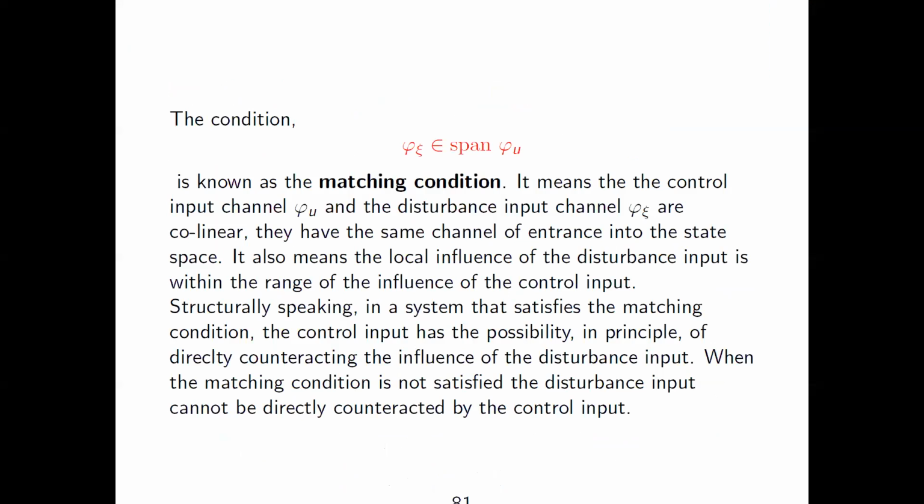Yes. Well, when you were talking about the matching condition, I thought you mentioned singular perturbation, and also the application to the DC motor. We understand that for a DC motor you have both an electrical part and a mechanical part, and they have very different time scales. The electrical part is possibly in the range of milliseconds or tens of milliseconds, but for the mechanical part the time scale is possibly in the range of seconds. So I understand this part. So you can use singular perturbation.